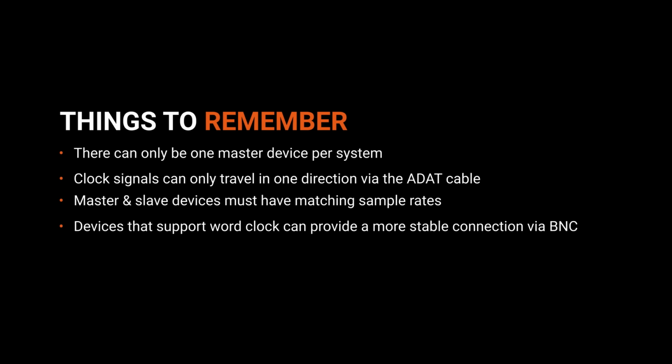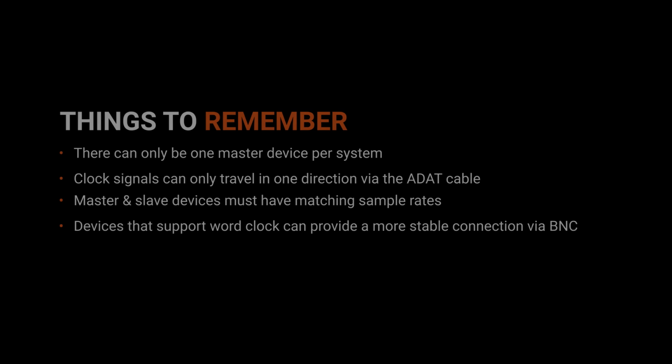Remember, only one master clock is allowed in a digital audio setup. Clock signals travel in one direction through the ADAT cable. Set the same sample rate on all connected devices for proper synchronization. Some devices might have additional clock options, like word clock, via a BNC connection, which can be used for more reliable synchronization in complex setups.